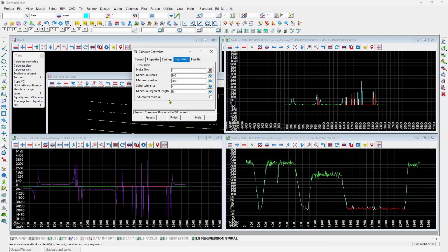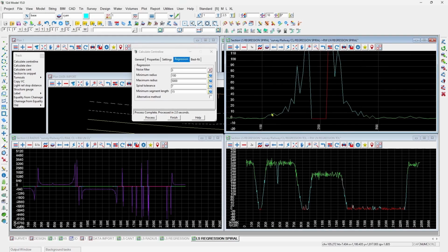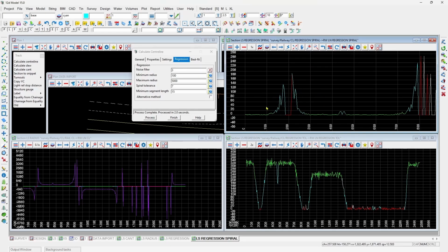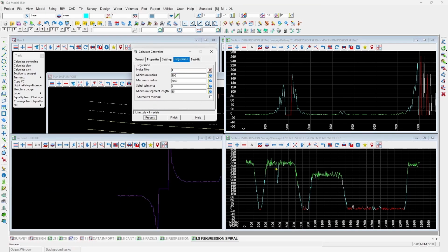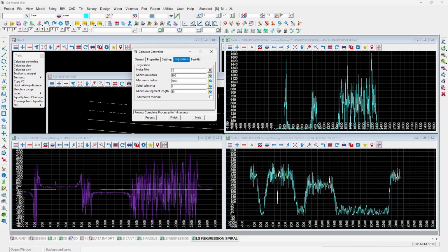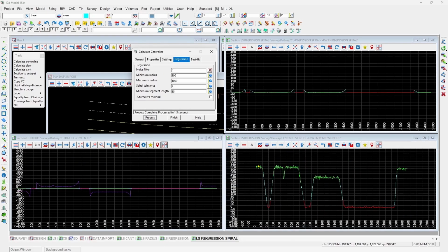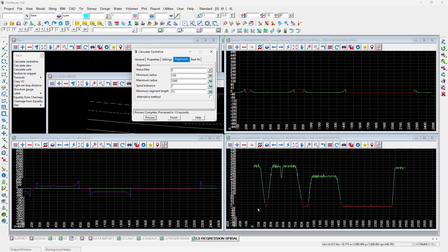so we have a spiral tolerance of 7 has been applied. So anything in this regression spiral view above 7 will turn that into a spiral. There's a noise filter here. If you've got perfect geometry that you're recreating, you might use 1, but you can see we can increase that to 5 in this case for a noise filter, and that cleans up this regression tolerance diagram a lot better. So you can see there's bands of colors here.